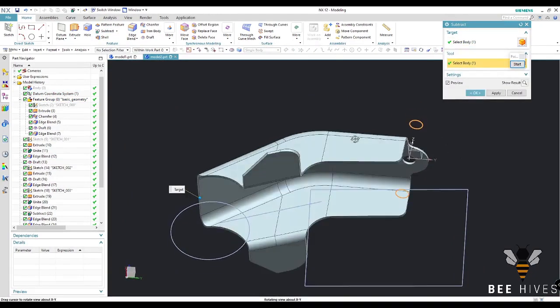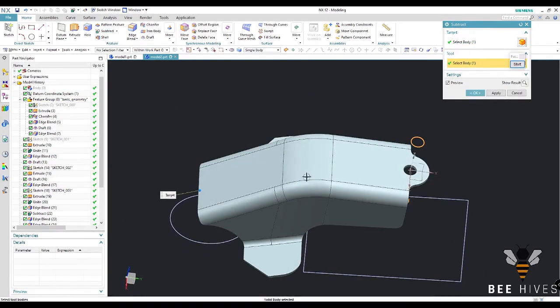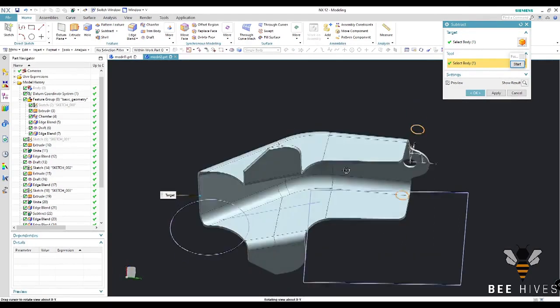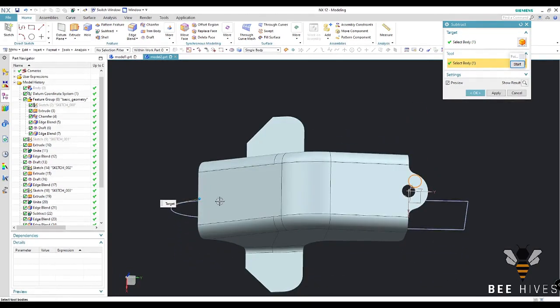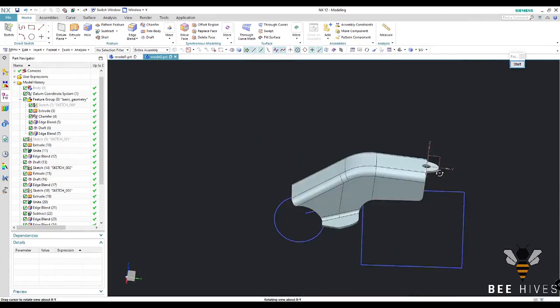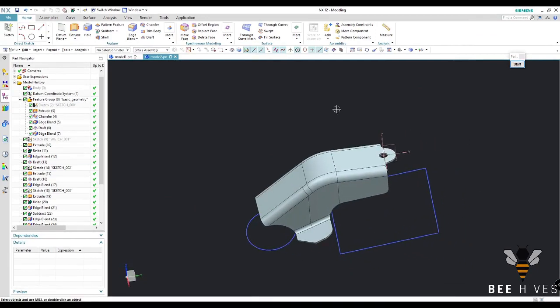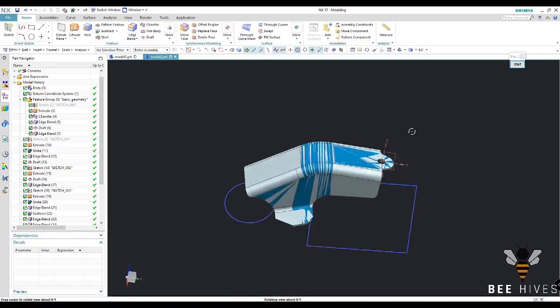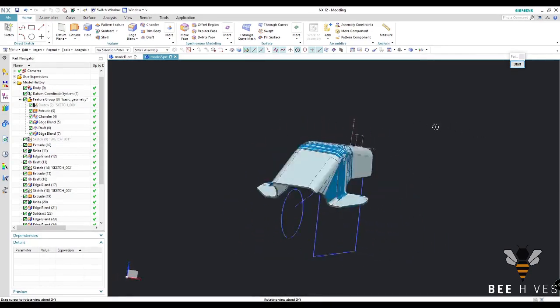So this is the good thing, to subtract the hole at the end. Many mounting holes or material removing holes or depressions you want to create, you can do it at the end after shell. It's completely fine. So this is the thing, and the remastered model is completed.